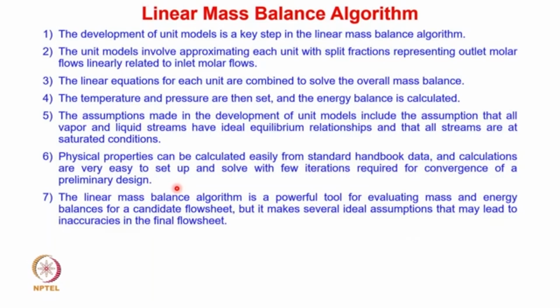So the development of unit models is a key step in the linear mass balance algorithm. Because of that, we have formulated the linear mass balance equations for different units. The unit models involve approximating each unit with split fractions representing the outlet molar flows linearly related to the inlet molar flows. The linear equations for each unit are combined to solve the overall mass balance. The temperature and pressure are then set and the energy balance is calculated.